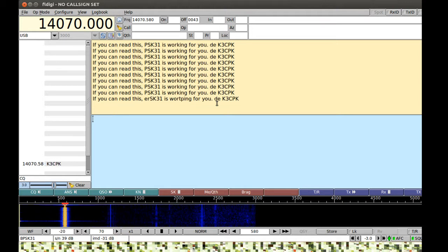Give me 1 second. Work? Cool. So I'm getting it now, but mine's just not really optimized. Hang on, bring GQRX up. See that gain, how it's 20 something? Bring it down to 0. Nope, it's too low. It should be 0. Perfect, right there. Leave it.